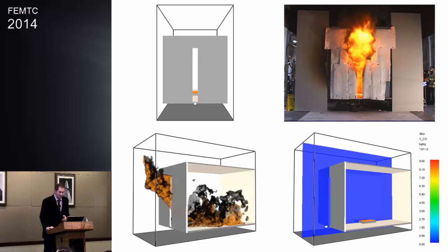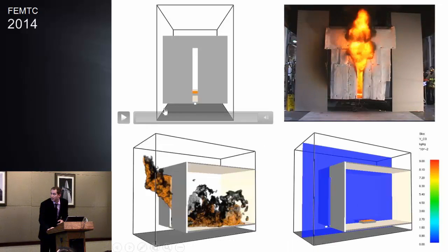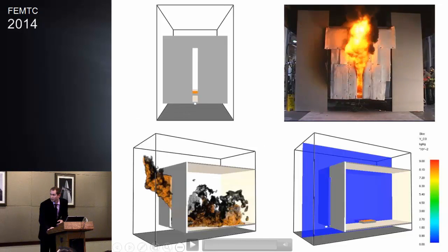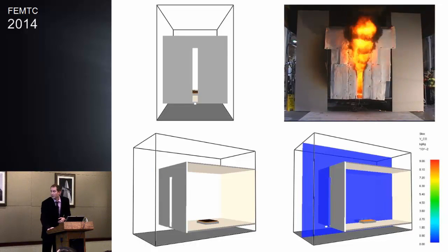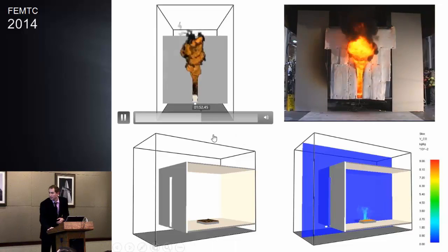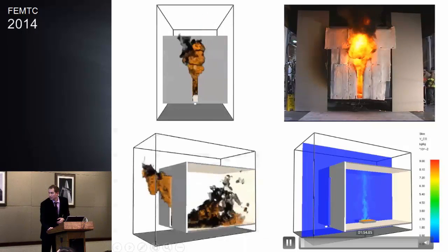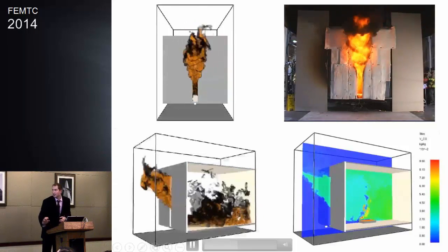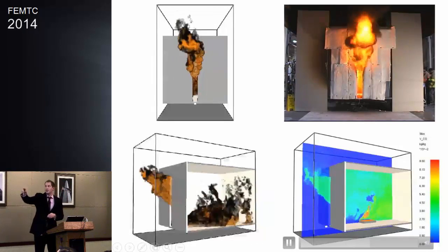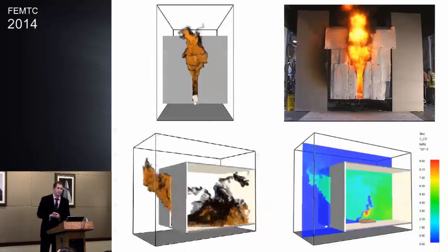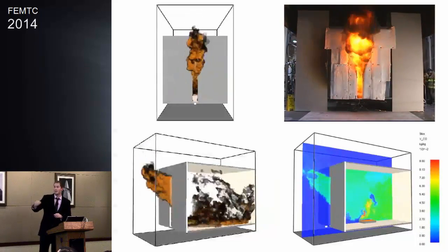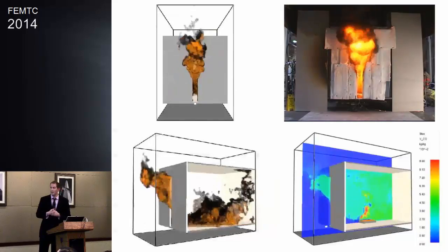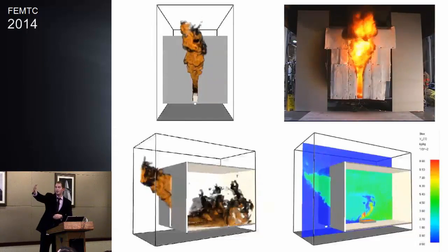As I promised, hopefully this will work. So we do have a fire video. It's fluctuating all the time. We've got CO concentration in the bottom right here, and then the top 2 are just the standard heat release rate visualization from Smokeview. And you can see in that bottom left that we are going under-ventilated in that compartment. We're just going to the door and along the bottom.